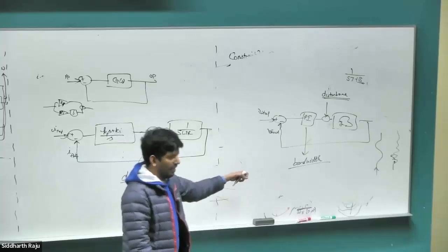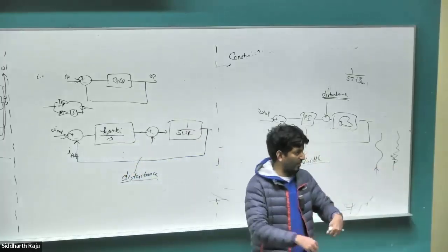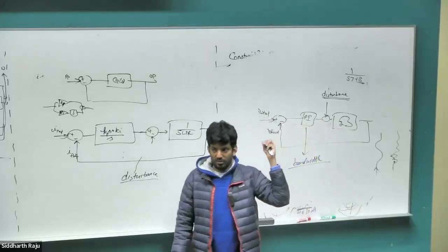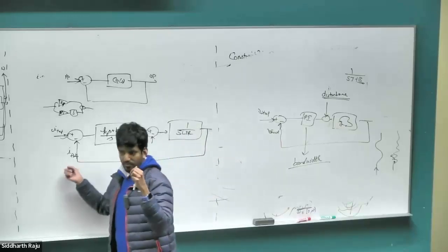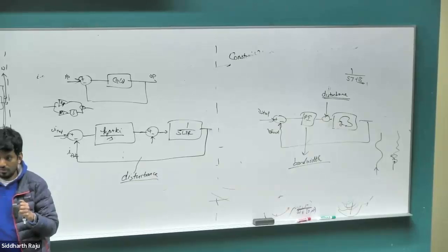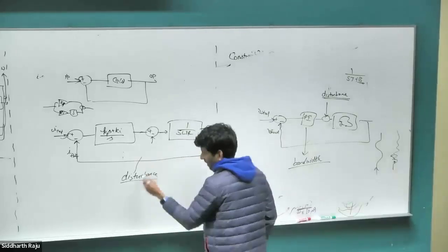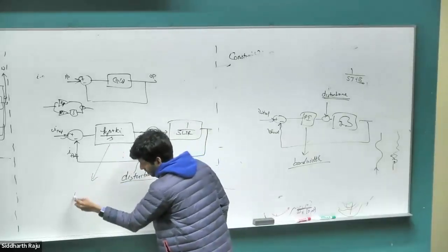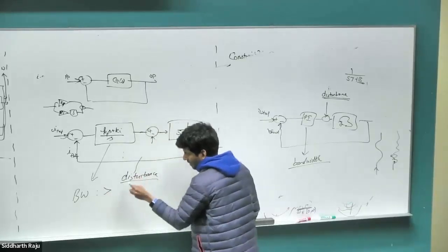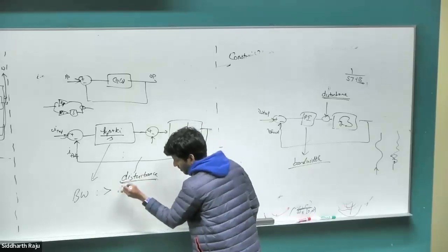What was the constraint here in the case of the car? That whatever external situation happens should not happen at a rate faster than my car can respond, or my controller bandwidth can respond. Okay, what would be the constraint for the EMF? Does your controller bandwidth have to be faster than the fundamental frequency of your motor? Right, perfect. So the rate at which our PI controller bandwidth must be greater than the rate at which our disturbance is changing, or the rate at which our EMF is changing.